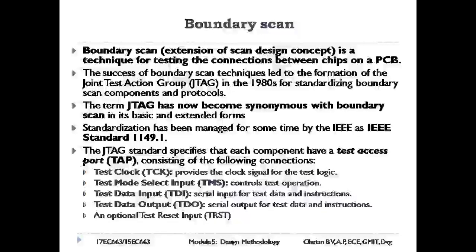JTAG, that is boundary scan, supports automatic testing of individual chips and PCBs containing multiple chips. Standardization has been managed for some time by IEEE as IEEE Standard 1149.1. The JTAG standard specifies that each component have a test access port (TAP) consisting of the following connections.